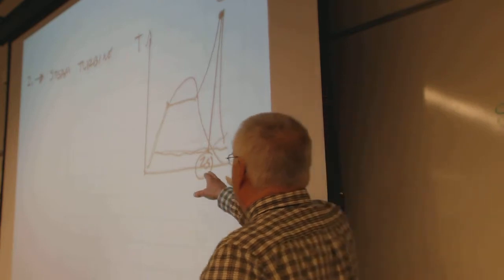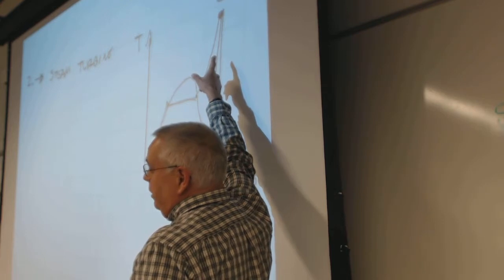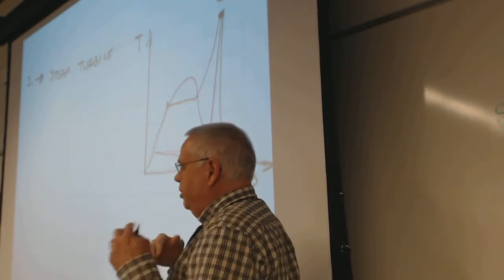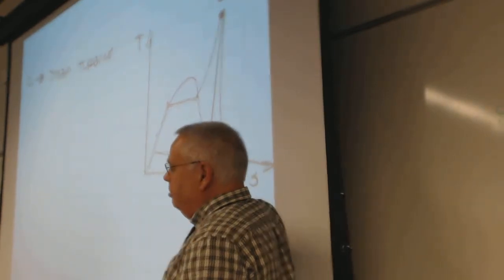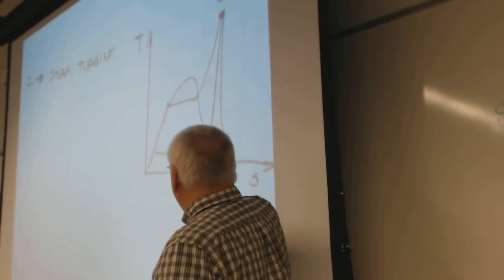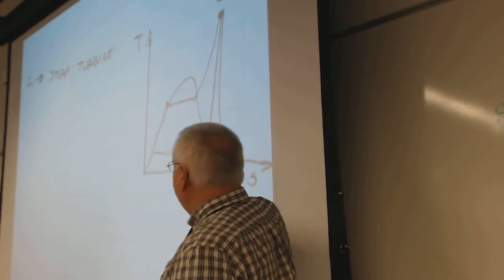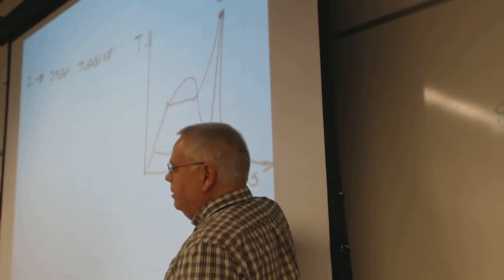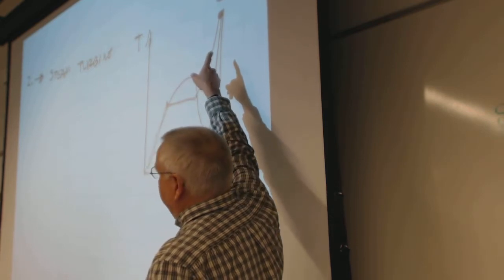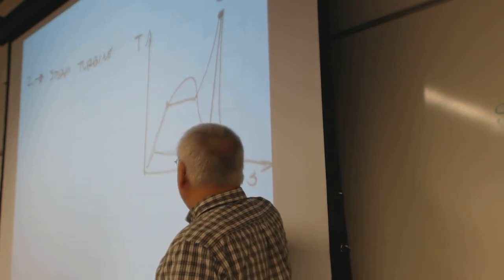We can find this using tables. How do we do that? If state 1 has an entropy value, this magic thing about entropy tells us where we land when we get to the new pressure. When we get to the outlet pressure, what's the quality going to be? Is it in saturation or superheated? That's all about finding an isentropic process, finding where that entropy value lands down here. So if I have an entropy value of 6.1 up there, if I find 6.1 on the chart down here, I might have to interpolate.